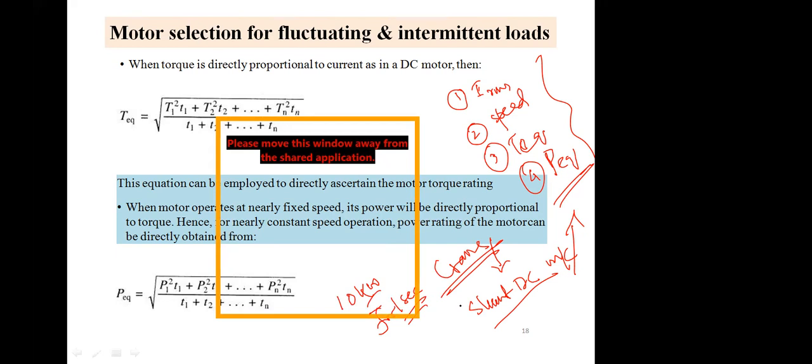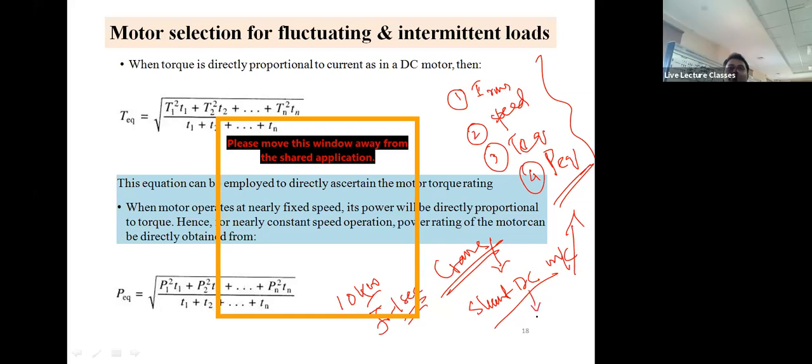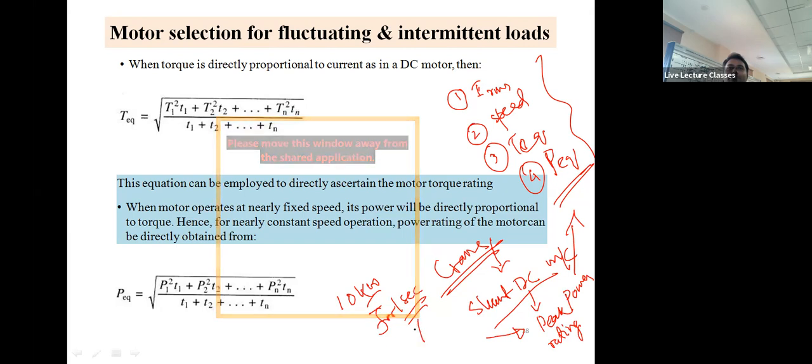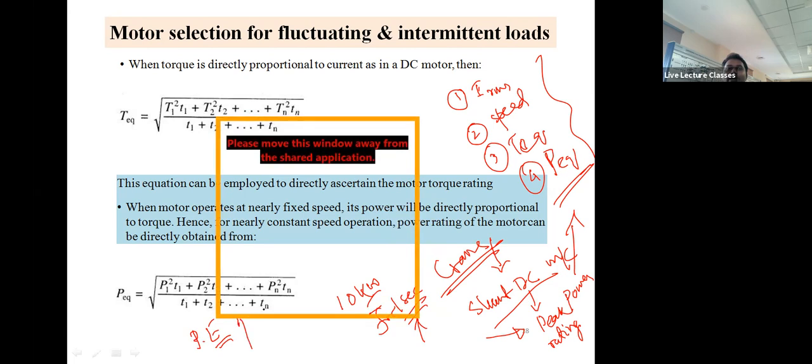No, it is intermittent. So you will be focusing on the peak power rating, the overload capacity, because you will be employing it for a very small time, 1 second. That's the good thing, so you will get the motor at a lower cost also. But the associated power electronics, if there is any, also has to be rated for such high watts. That is another concern, right?